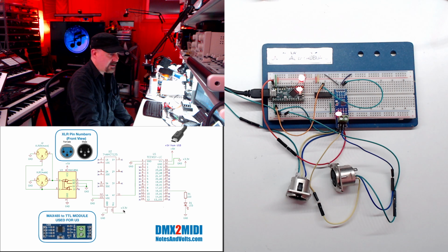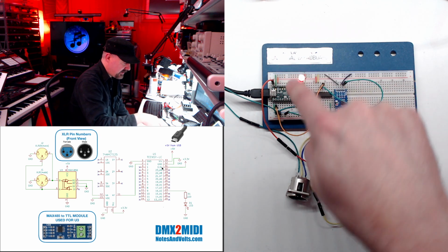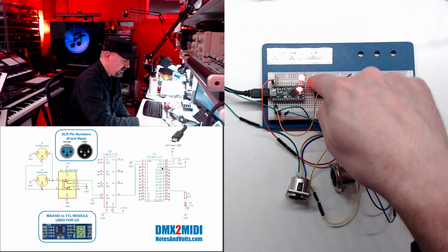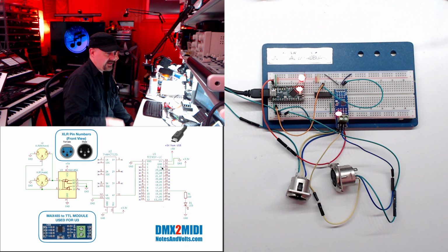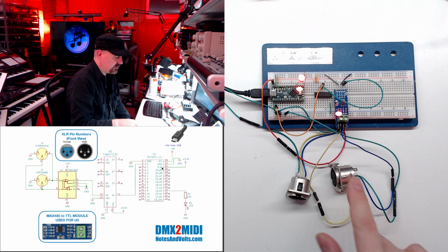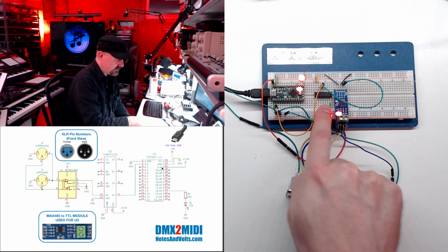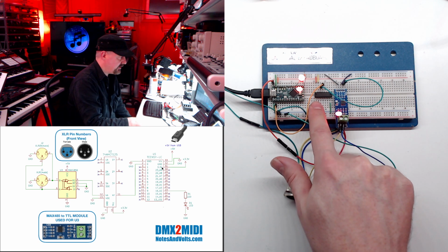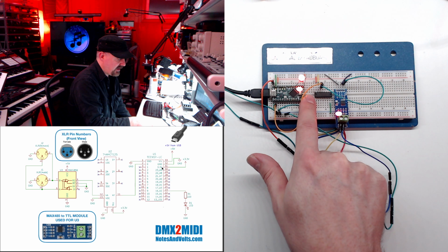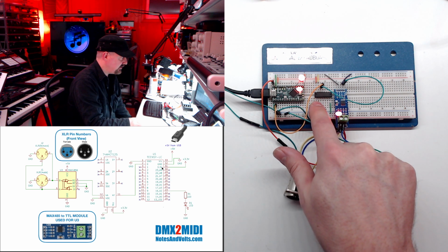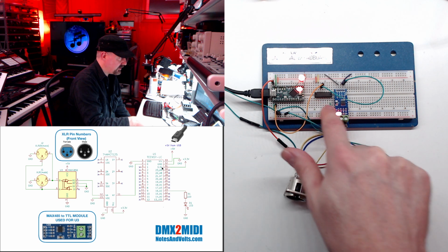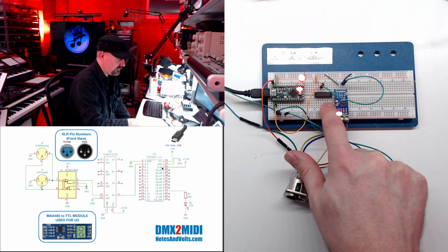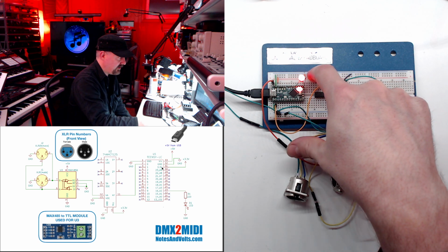To do that, we're going to power it with 3.3 volts that we can take from the 3.3 volt pin on our Teensy. So there's our 3.3 volt pin. I actually ran it to this red strip, and there you can see it going into pin 14 of our chip. We also need to give it a ground, and that is on pin 7. There it is right there, going to the ground strip to our Teensy's ground. Remember, when you count the pins on these chips, you'll find a notch on one end, and the pin directly to the left of that notch is pin 1. Then you go counterclockwise around the chip. So that's 1, 2, 3, 4, 5, 6, 7, 8, 9, 10, 11, 12, 13, 14.